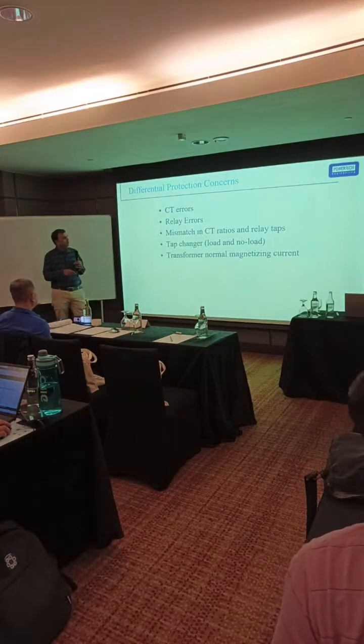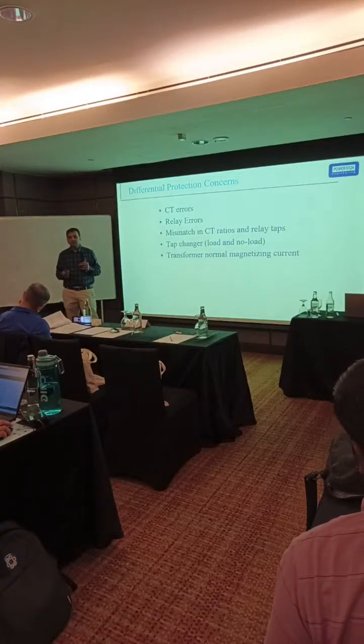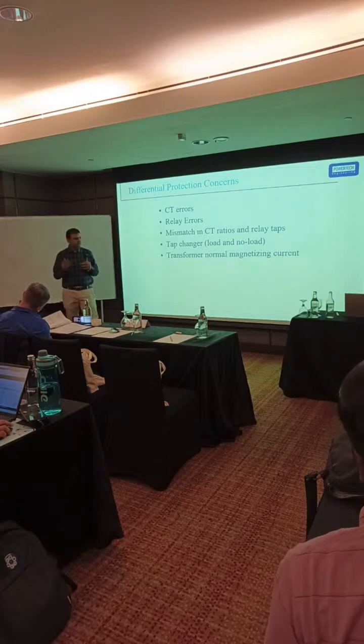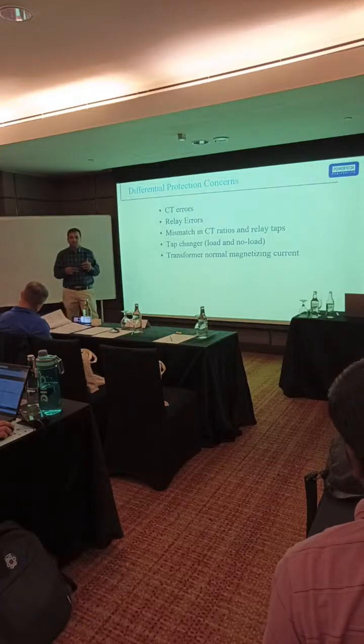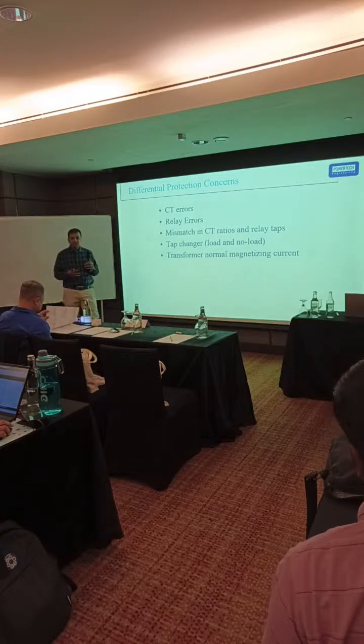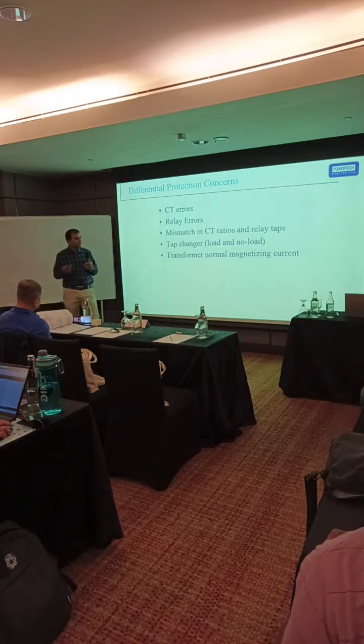Transformer normal magnetizing current. When we charge the transformer, we learned a lot of things yesterday. While charging the transformer, there is a heavy current flow for 3-4 cycles. Due to that, differential may operate. How we compensate, we learned yesterday.